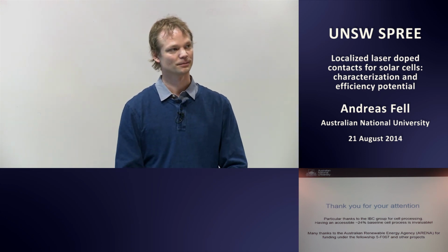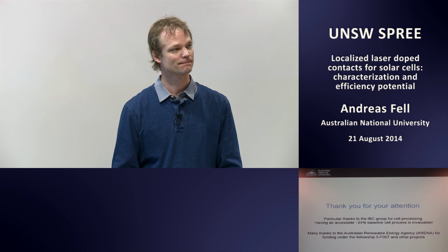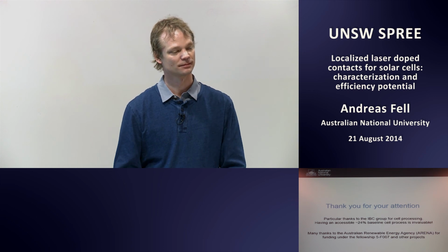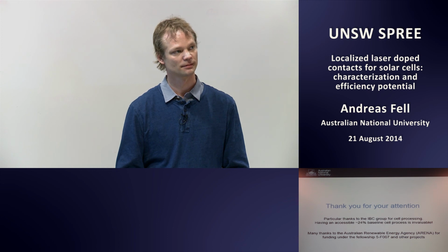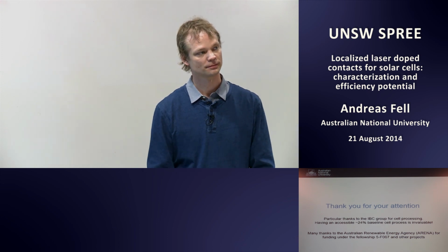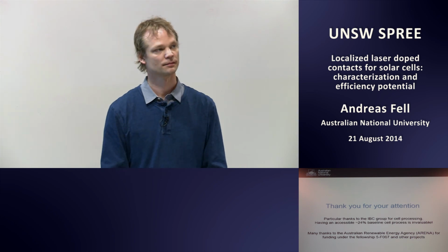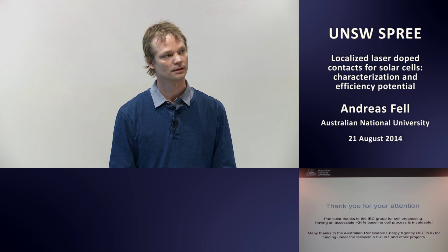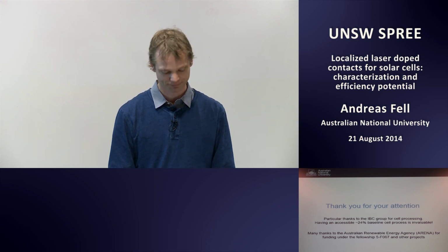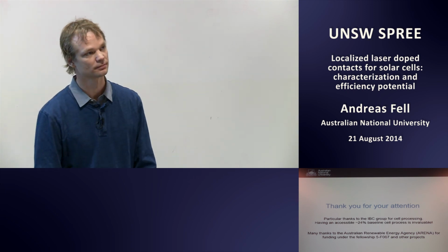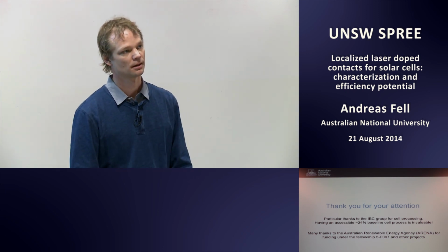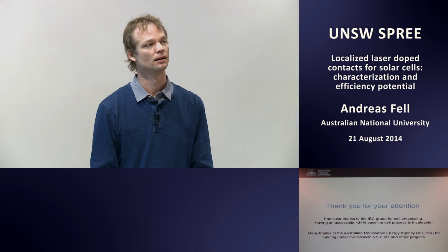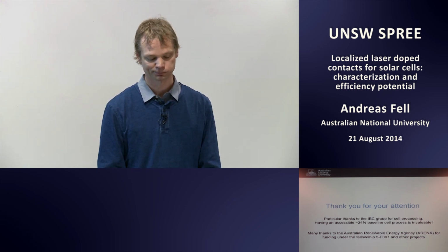It was very informative. So you mentioned for your recombination modeling that you don't have anything really to compare it to. Theoretically, in the limit of a small pitch with a similar contact area fraction, you can assume that you get an effective surface recombination velocity from just assuming that there are no 3D effects from carrier diffusion. Do you know when that simple assumption diverges from the model that you need?